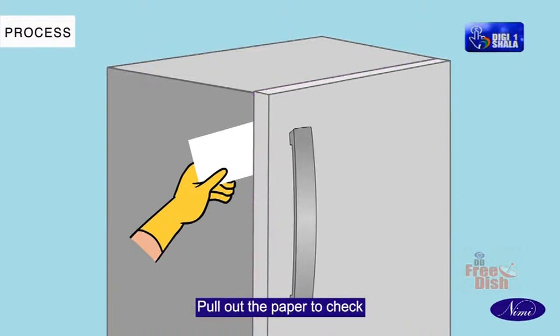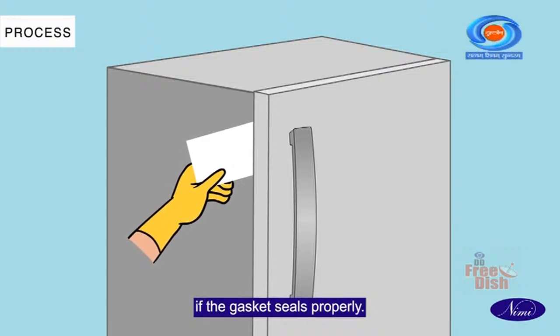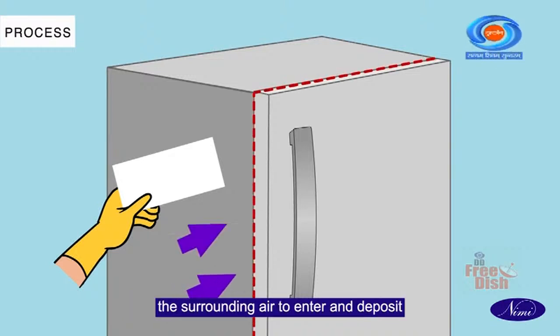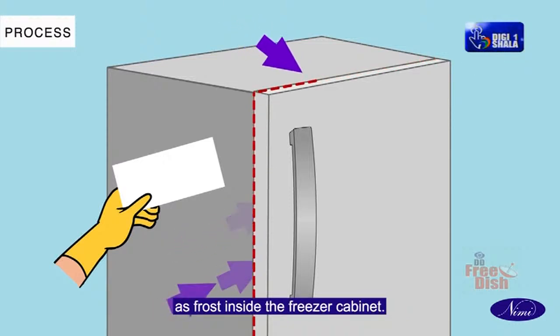Pull out the paper to check if the gasket seals properly. If the paper comes out easily, it indicates a sealing issue, allowing moisture from the surrounding air to enter and deposit as frost inside the freezer cabinet.